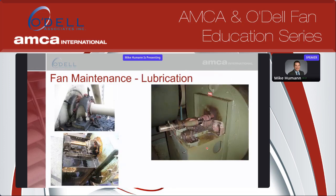So when we talk about lubrication, a lot of people say there's no such thing as too much of a good thing, but over lubrication is actually a really big issue with fans. If you over lubricate, it can become a heat issue and a housekeeping issue, and it can lead to bearing failure. So it's really critical to make sure your lubrication schedule is correct and you're lubricating the fan properly.